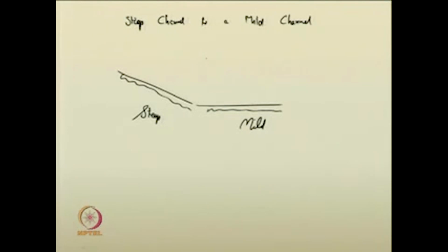So, you have to see that the slope of the water surface profile can be positive only in zone 1 and zone 3, it has to be negative always in zone 2. So, keeping all those criteria, what are the profiles you can imagine? You just do it as homework. Let us see, and I will discuss this. More discussion on this aspect will be in the next module.